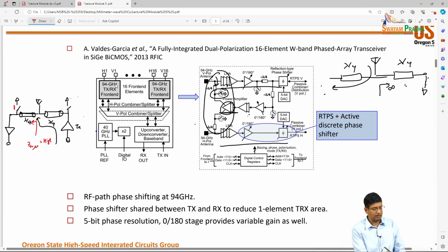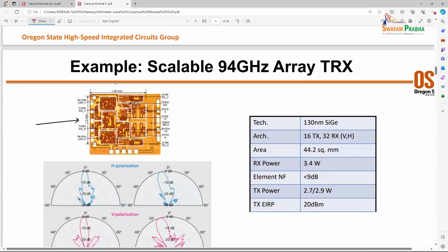So firstly, low power goes in, and then right at the input to the LNA, you're shorted in, low impedance anyway. So the voltage swing is reduced. This was at 94 gigahertz. It was in 130 nanometer CMOS.